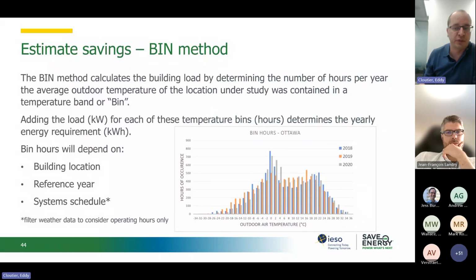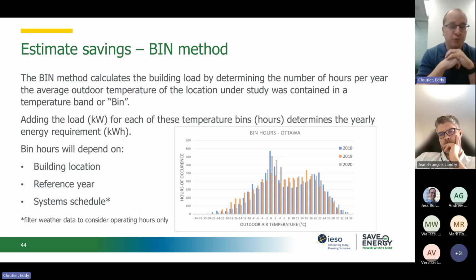Therefore, if a recommissioning measure makes it possible to reduce the heating or cooling load, or even the humidification load, for example, this data will make it possible to make energy saving calculations based on outdoor conditions. An example of such a measure would be to introduce a temperature setback in winter in a building that did not have one previously.